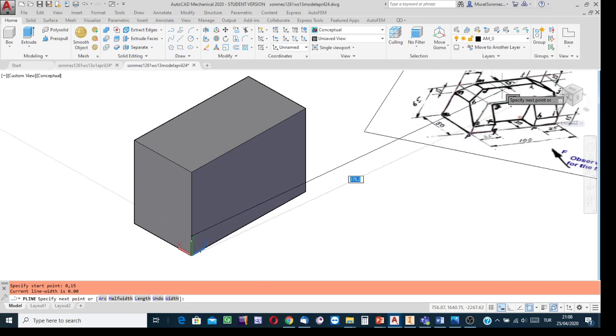Since the upper boundary is 15 millimeters away with respect to the back side, the coordinate of the terminal point of the edge of the surface with respect to the available origin, yes, since the point is at the positive side of the x-axis, delta x is positive. Write the value 50 minus 15, it makes 35. It is positive. Write 35.